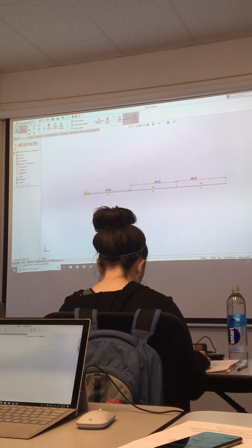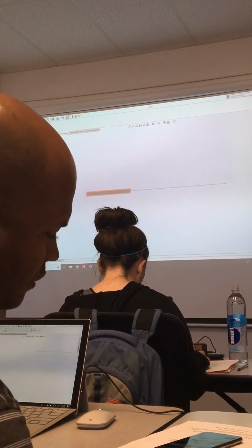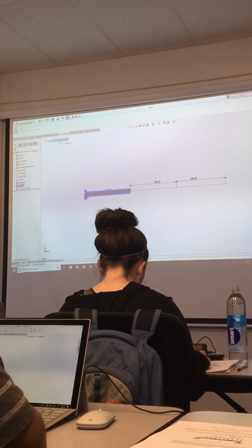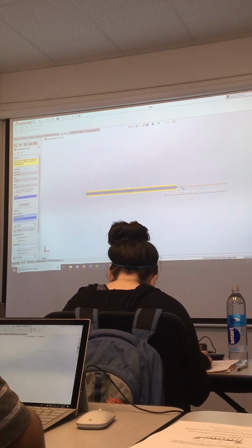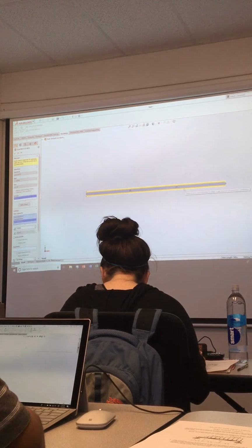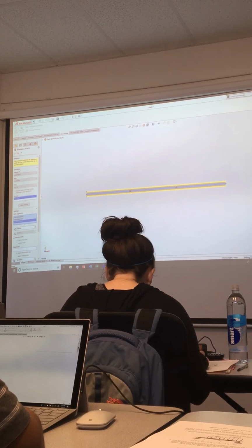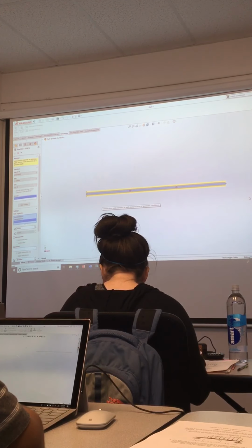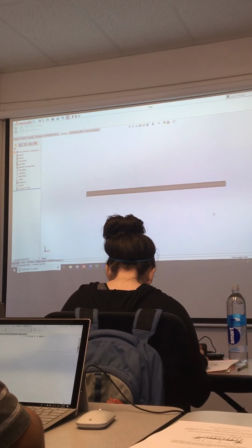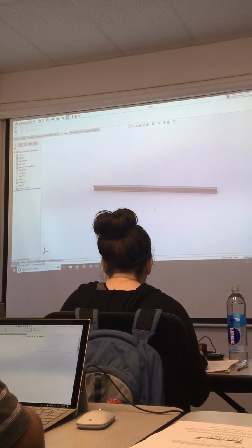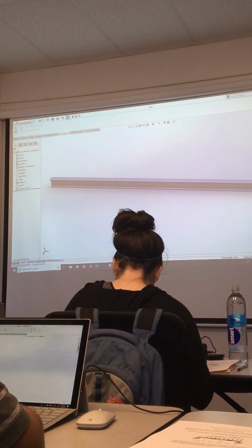Okay, then I get out of the sketch, and then I have to go in and edit this guy, this one, and in the group down here, path segments, I've gotta click on these other ones. So in this path segment in your group, where you're defining one of those, you have to pick other segments. And so now I've got 3 segments. And I can say, okay, and I have a beam that's now the same length, but it's broken up into 3 chunks.